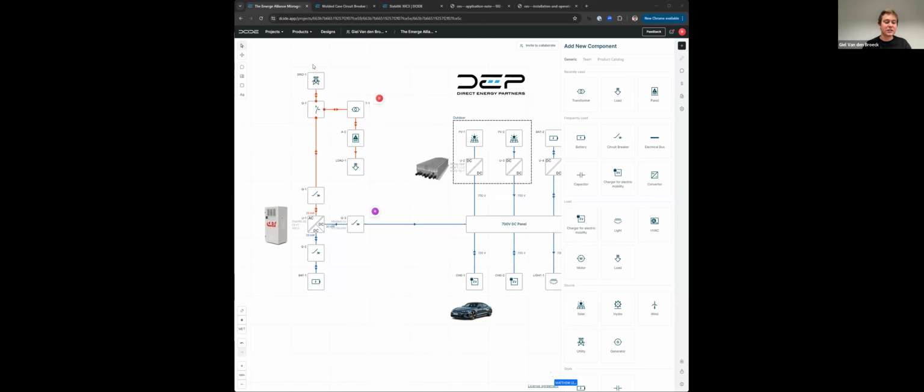All the electronics will continue to function, and you don't need complex transfer logic and transfer switchgear to switch from grid-connected to islanding mode. Everything connected on the DC side will receive power and will not even experience that grid outage.